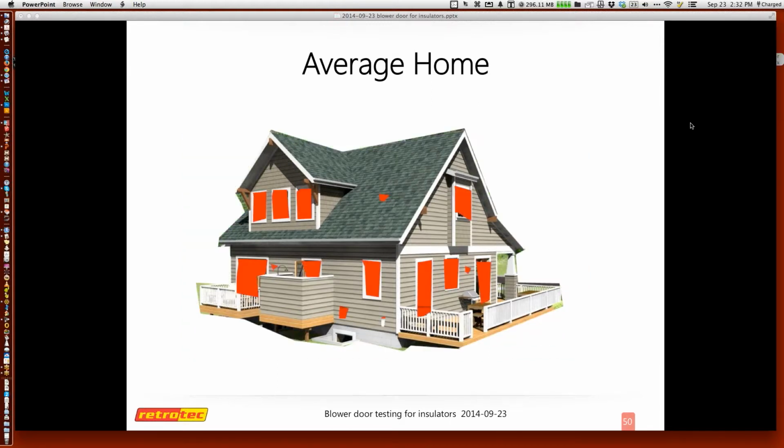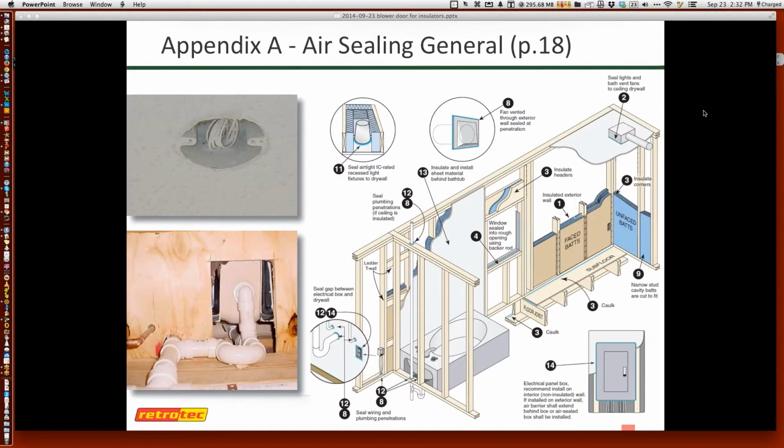So now we have all these windows and doors and separations and vents to the roof and receptacles and connections for AC units, and a variety of stuff that's also inside the house, which doesn't show up here, is all of the wall framing that we have that has connections to the attic or crawl space directly in the inside of the house. So we kind of make Swiss cheese out of the homes we build, and they're expecting somebody to be responsible for the air sealing.